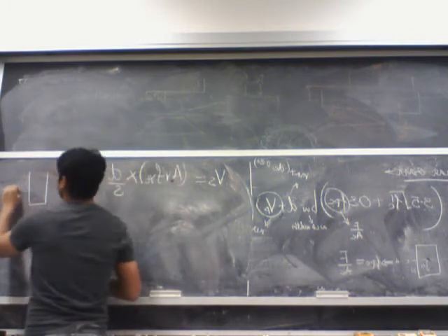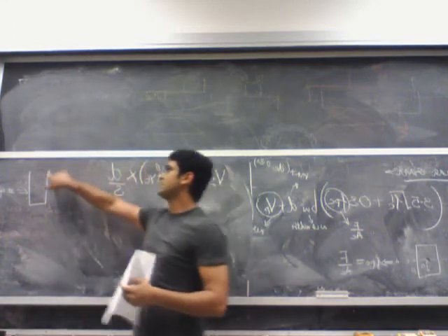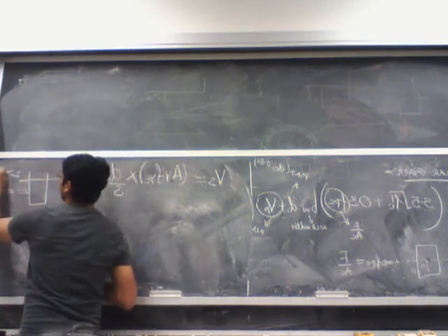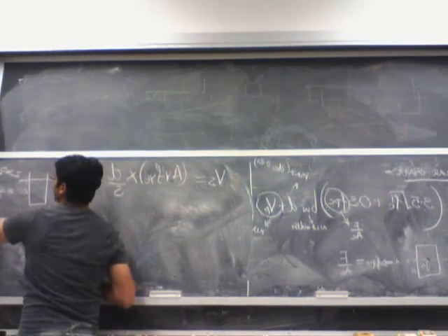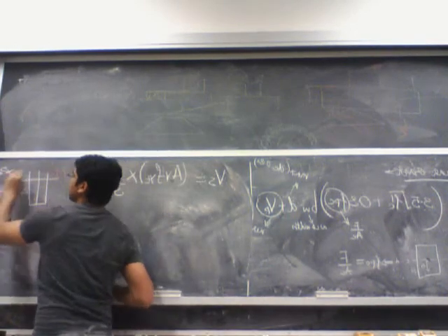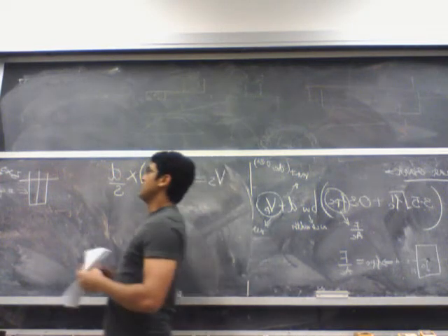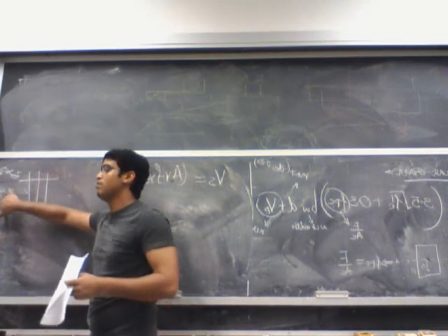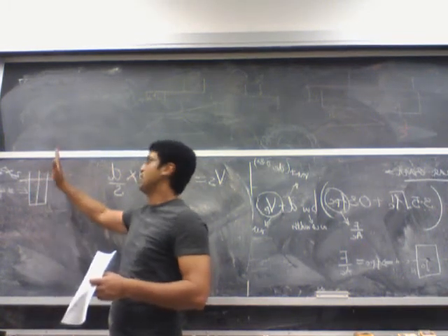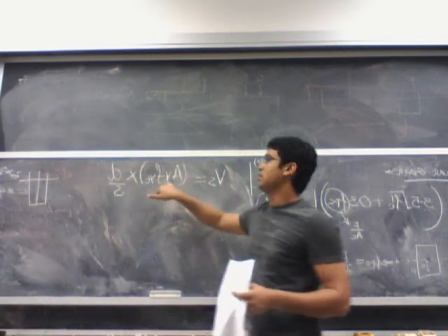and let's say I use a number 4 bar. Since I have 2 legs of shear stirrups, my Av is actually 2 times 0.2, where 0.2 is the area of one number 4 bar. If you provide 3 legs, it becomes 3 times 0.2. So it's not just the area of one bar that you provide. It depends on how many legs of stirrups you are providing at that cross section. So that total area is your Av.